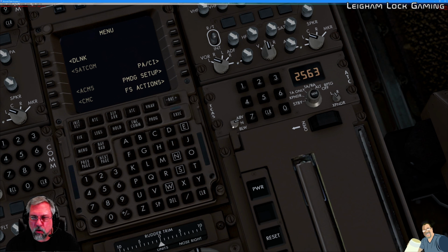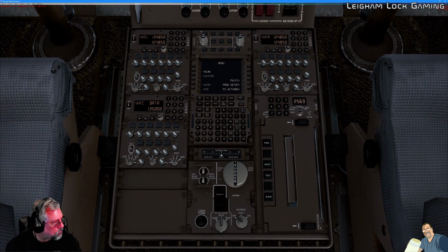And since we're going to be taking off here in a moment, the TCAS has a normal, above, and below. For takeoff, we want to be looking for aircraft based primarily above us. In cruise, we would go to the normal or neutral position for looking in front of us. And then when we start our descent into JFK, we'll go to the below position, looking for aircraft that we might be descending down upon. So we can go ahead and put that in the above position now, just so I don't forget about it. And that completes the first officer pre-flight checks.